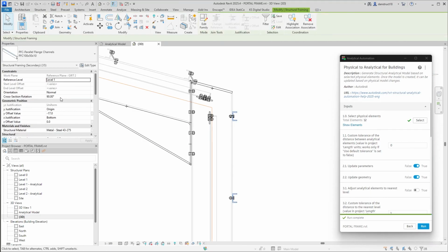In this case here, I'm just going to set the cross section rotation here to 180 degrees since it's in the other direction. There we go. I'll set the Y offset value here to -40 and the Z offset value here to -100. Then click apply.